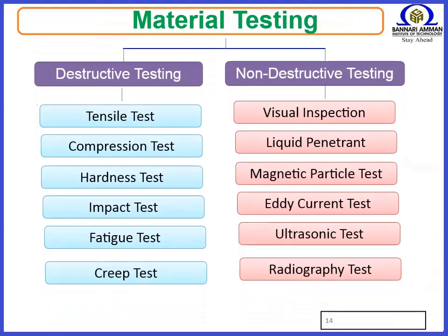Destructive testing, DT, is a form of object analysis that involves applying a test to break down a particular material to determine its physical properties, such as the mechanical properties of strength, toughness, flexibility, and hardness. Types of destructive testing are: tensile test, compression test, hardness test, impact test, further categorized as Charpy test and Izod test, bend test, fatigue test, corrosion resistance test, wear test.